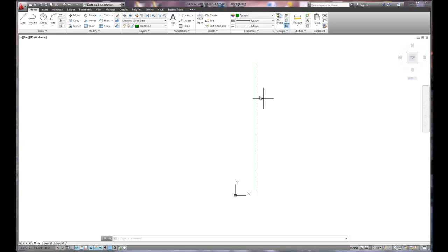So where do we begin? Well, we need to change our centerline layer to a wall layer. We're going to start with the wall of the doghouse. Now this doghouse is no slouch of a doghouse. It's going to have a couple of very unique features. First off, we're going to start with the line command. We're going to arbitrarily pick a point. Okay, so we're not specifically going in any XY position location. We're going to just pick a point here, and we're going to make this line 4 feet wide.